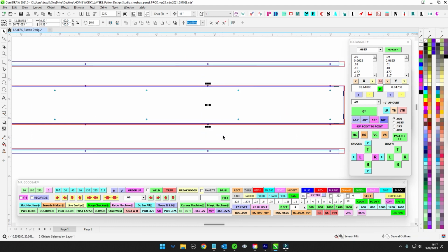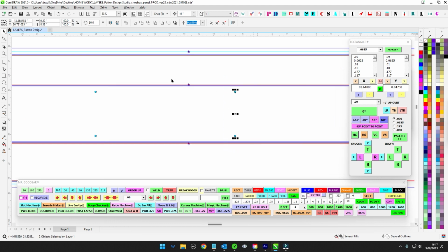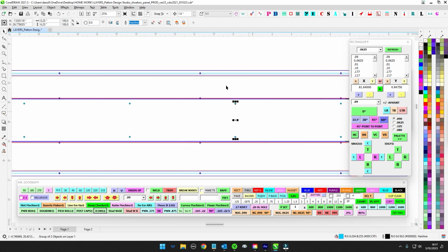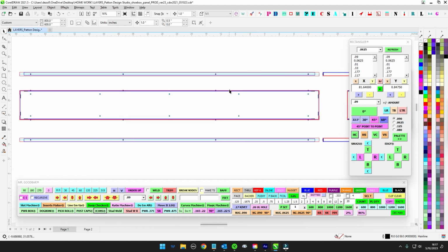So obviously having these screws be this far, we've got 6 inches. So the stress of this screw going across the backer to this screw is not that big a deal. But when I am less worried about how something looks and I'm building something for strength, then I will work backwards, where I will put the mounting first, right?